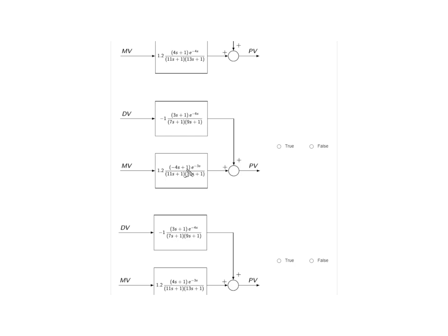In this fourth example here we have a negative lead time constant, so here we have, between quotes, an unstable zero. This process has an inverse response. If we construct the feed forward, it will be d over p, but the feed forward will go through the process. What we'll do is cancel this, between quotes, unstable zero, and this goes against internal stability, so the ideal feed forward cannot be implemented, it cannot be realized.